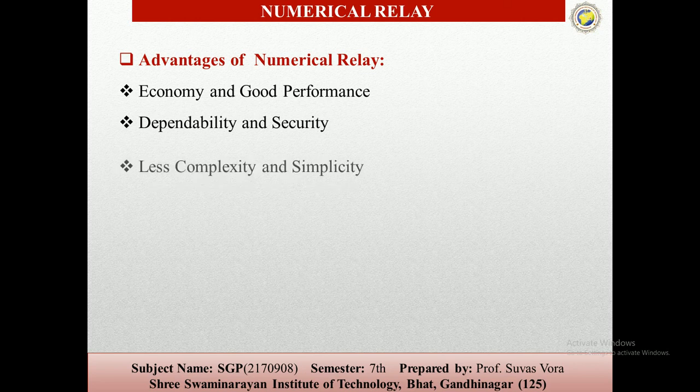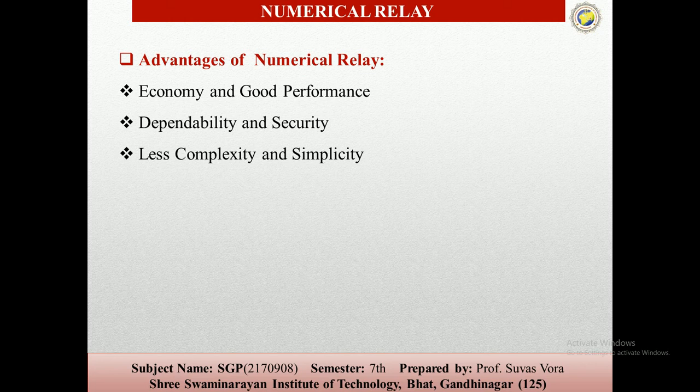When the current exceeds the actual rated current, the CT senses the current and operates the relay coil. This relay coil is connected with the plunger, and the plunger closes the circuit. The tripping coil is energized through the batteries, and the circuit breaker opens. So these are the basic protections for the overcurrent relay. Now we can see the numerical overcurrent protection relay.